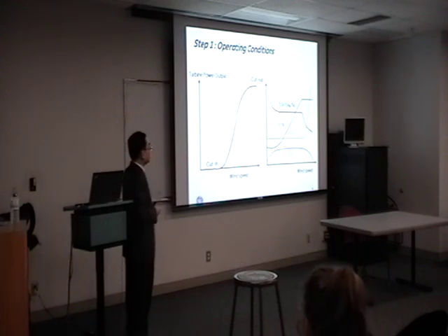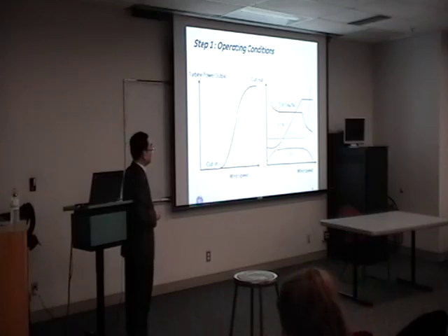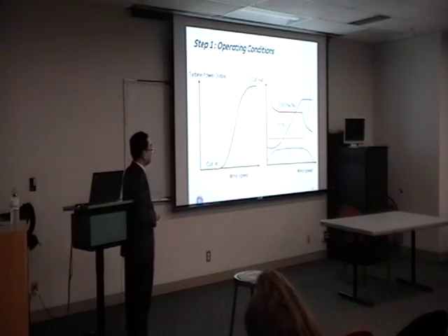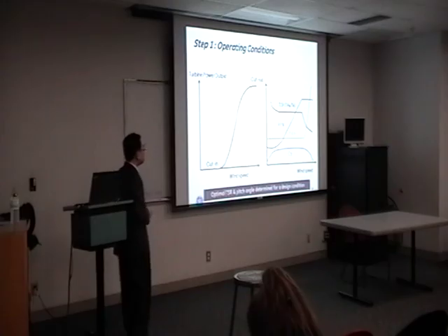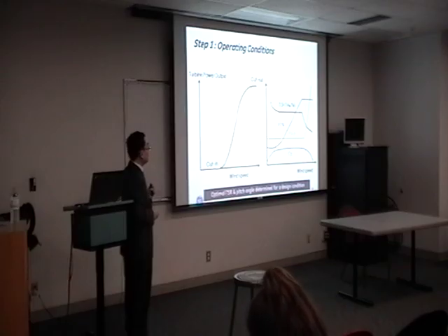And this is CP, or power coefficient. CP remains at the maximum for a constant tip speed ratio and constant pitch angle. Then CP drops at very low speed and it drops at very high speed. So it's very important to determine the right values of tip speed ratio and pitch angle.